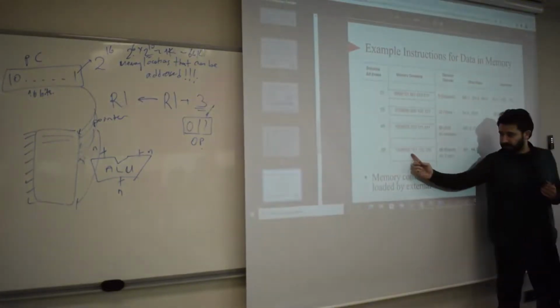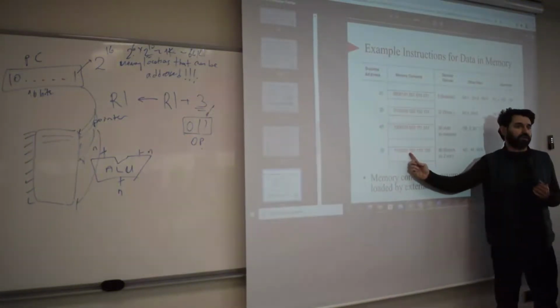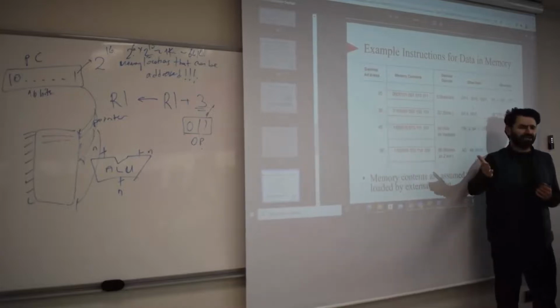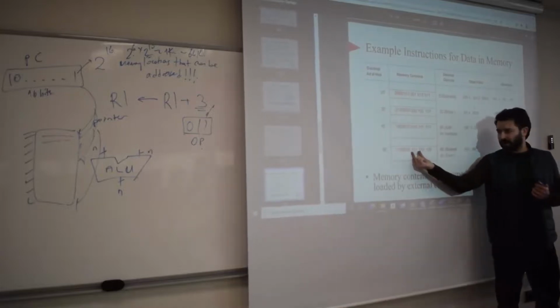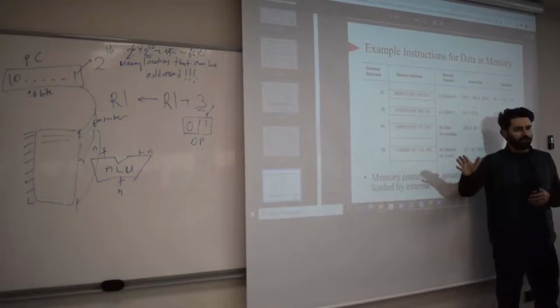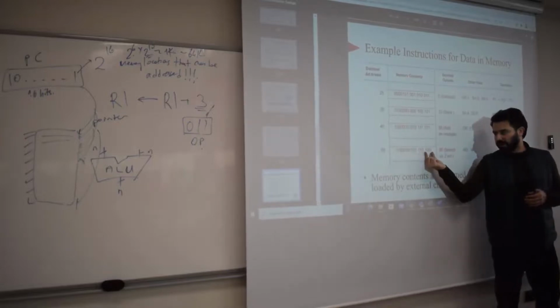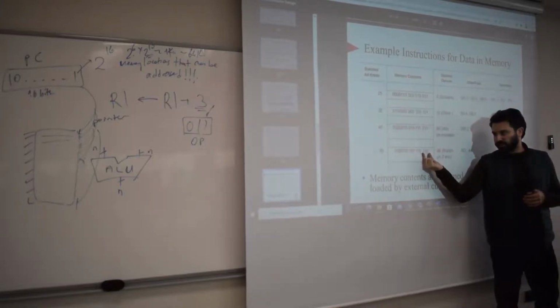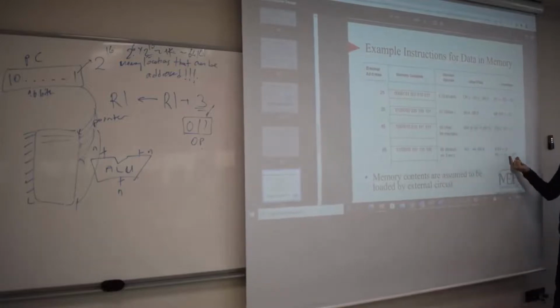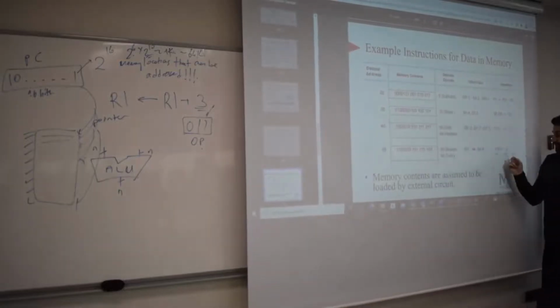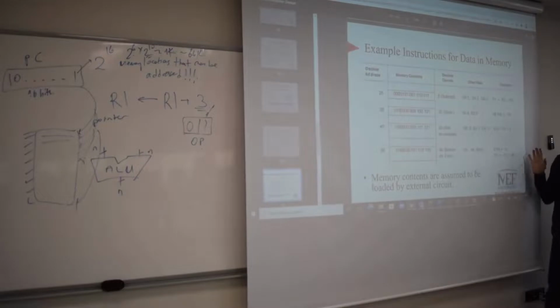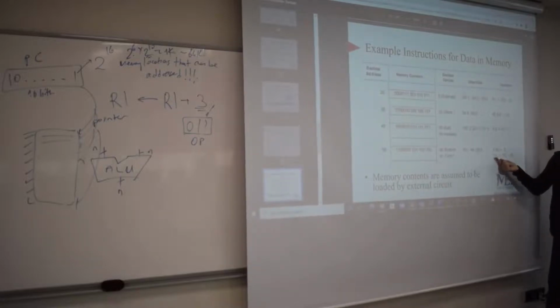You can actually see that this one tells you that it's a negative number. You can go ahead and check it if you like, if you don't believe me. And please don't believe me. Go and check yourself. This 101 is concatenated with 100 to make up minus 20. And that minus 20 is sign extended, which is not shown here, to make it 16 bits. And then it is added to the current value of the program counter, whatever that value is, okay? And the result is written to the program counter.